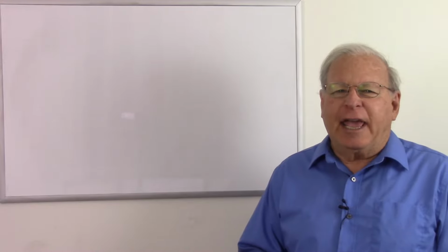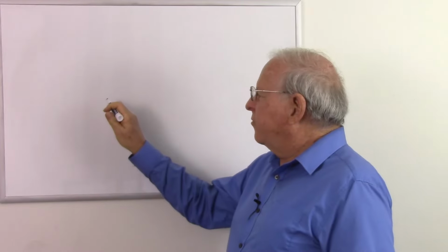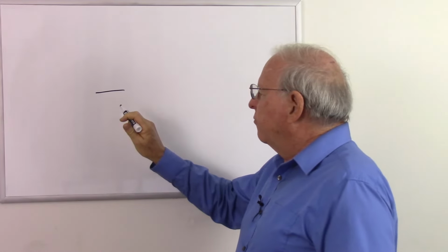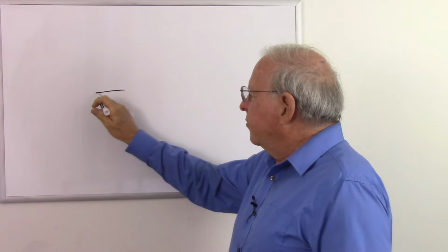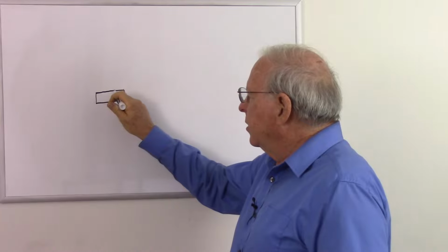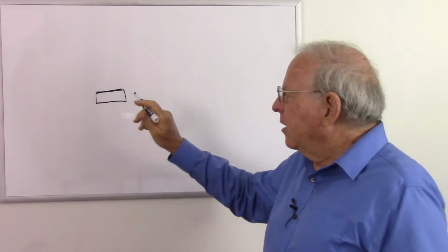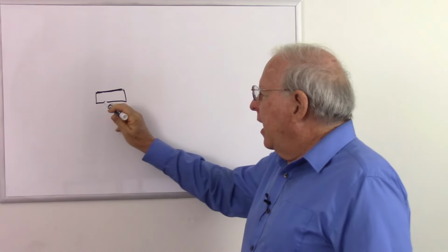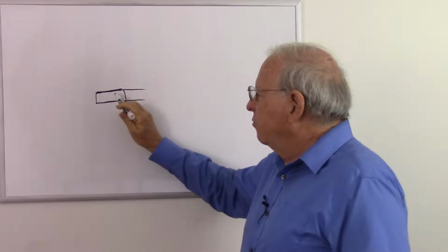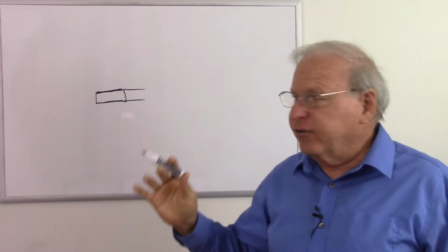Let's first look at a typical dynamic or even capacitor microphone. In the case of the condenser or capacitor type, there is a sealed capsule, one of which has a metal or foil plate, or perhaps aluminized mylar, that can vibrate, and it's insulated from the back here, so we have two conducting pieces separated by an insulator, and that makes a capacitor or condenser.